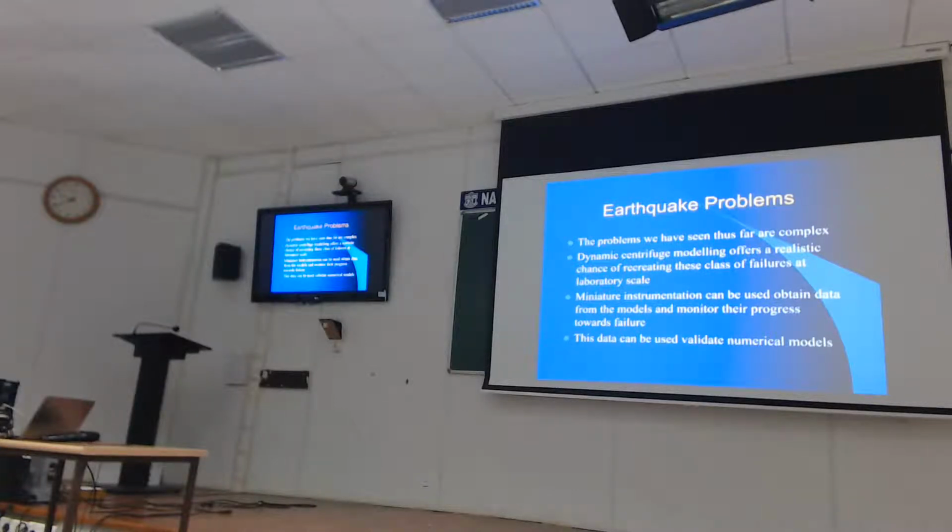The best thing you can get out of a well-conceived centrifuge test is the failure mechanism. And I'll give you examples with piles later on. But for any problem, when you start new, that's what you're aiming to do. You're aiming to capture the failure mechanism. Once you know the failure mechanism, then you can run the numerical analysis or any other limit equilibrium analysis even, because you know you're capturing the right failure mechanism.